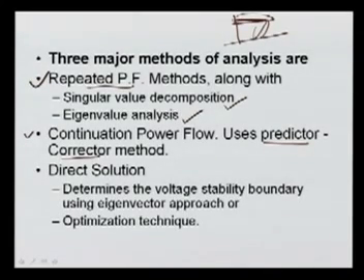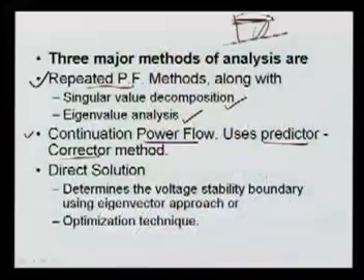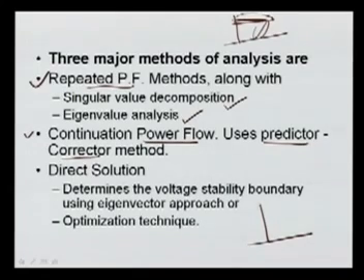But in the continuation power flow, I was explaining its advantage over the repeated power flow method. I will explain how we get the power flow solution using the continuation power flow method, with the steps of the predictor as well as the corrector. Here in this PV curve, we can get even the lower portion of this curve as well.